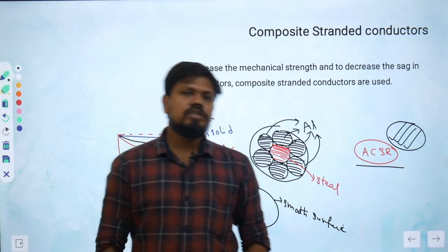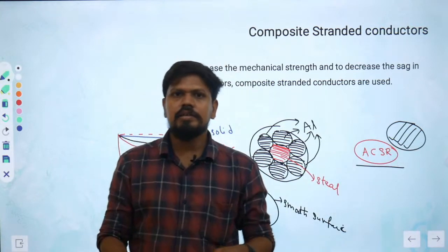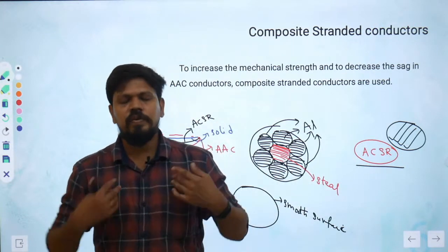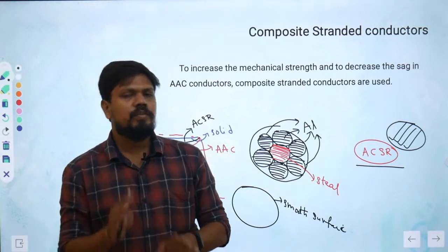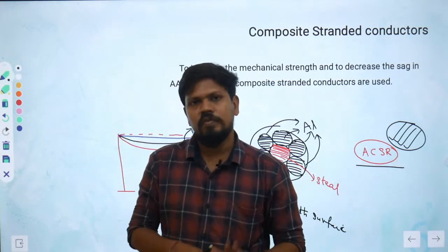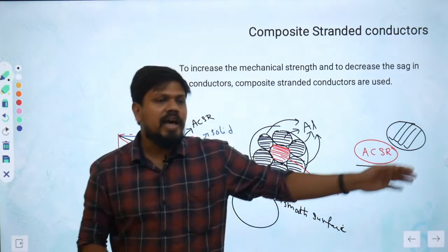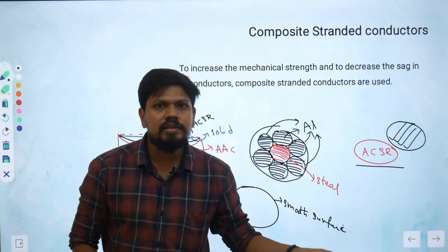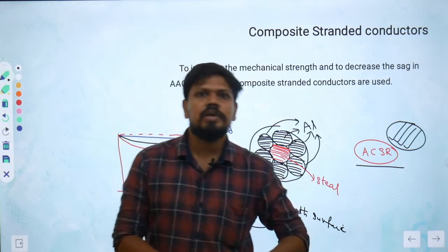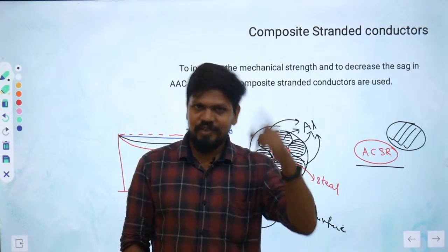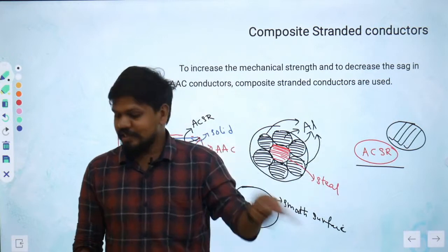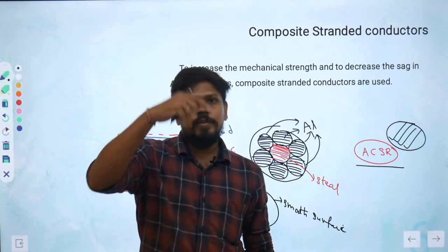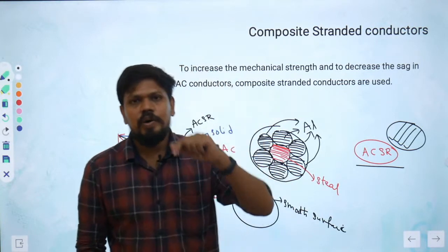Now see, for example, every day in a year I need 100 megawatt for my application. Some loads I have, and for those loads I need 100 megawatt daily. So which power plant can be run daily? A power plant on the Ganga river or one on the Krishna river? A power plant on the Ganga river only, wherever water availability is more and water flows continuously throughout the year. That type of power plant is nothing but a base load power plant.